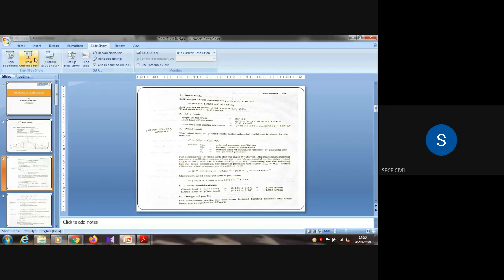Now you can see in this slide. The slope of the truss is 26° 34 minutes. Therefore, for the live load of the truss, we already saw in the code book it's 0.75 less than 0.02 for every 10° increase. Here they did 0.75 minus, for the next 10 degrees they reduced 0.01 times, and after the 10 degrees they reduce 0.02.